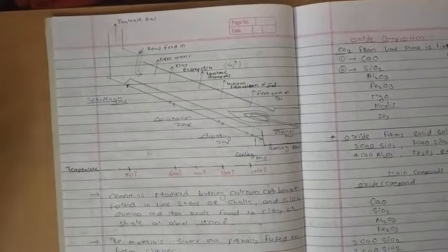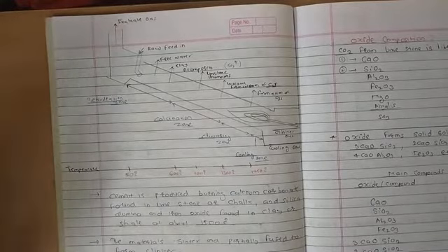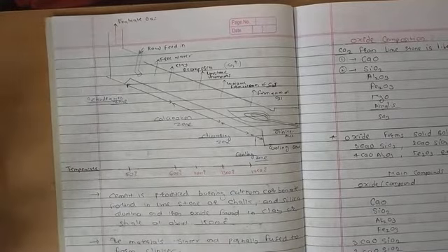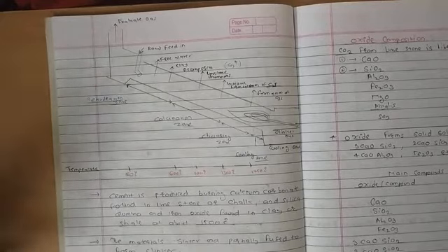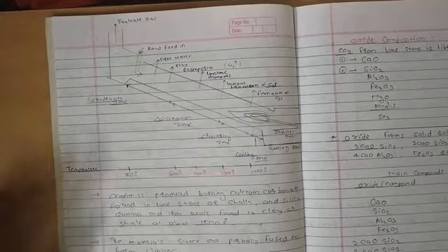After heating at a very high temperature, the water in between them evaporates, but they are still in the form of small balls. We have to grind them to an appropriate size and shape, then we can get a very soft cement material. The clinker is cooled and ground to a fine powder to form ordinary Portland cement.